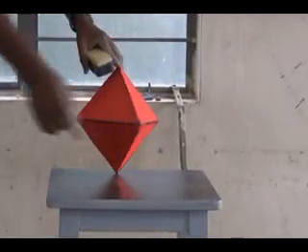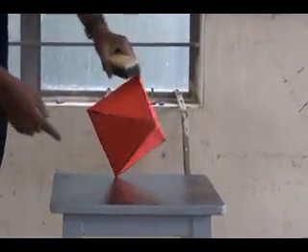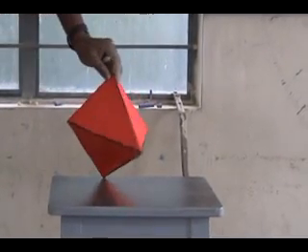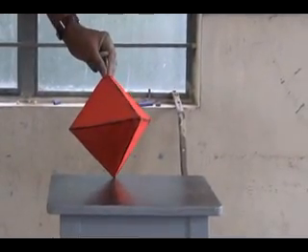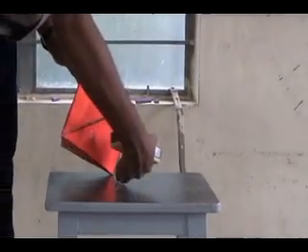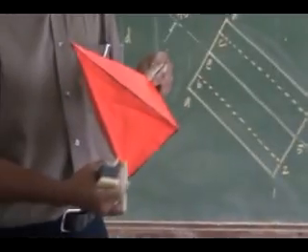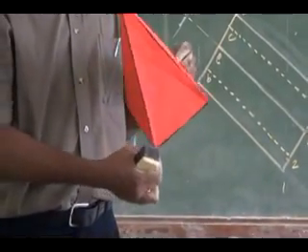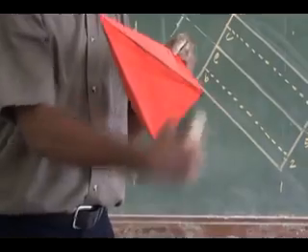Here, it is a square pyramid, resting on HP like this, with a base corner resting on HP. I have 4 base edges, and for the resting corner I have 2 adjacent base edges.